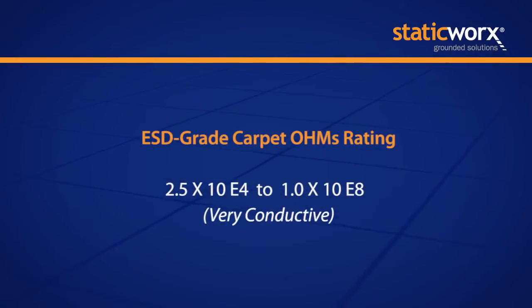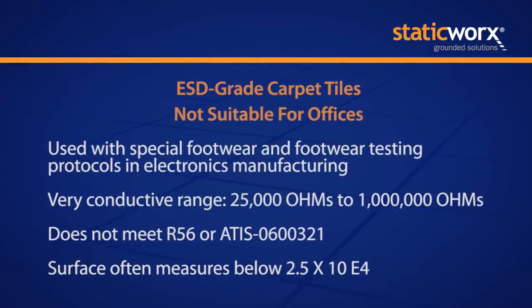The problem with this type of carpet is it has an ohms rating that puts it into the very conductive range. But when we're talking about using carpet in a real-world environment, we're talking about people coming in wearing high-heel shoes, wearing work boots, wearing flip-flops. You're not in a situation in those environments where you have the ability to know whether you're safe or not based on any kind of testing. So this has created a need for a third type of carpet.